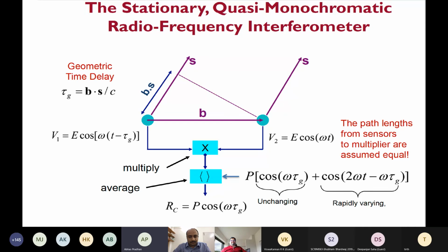So is this calibrated beforehand? Is this correction determined before, or is there a real time correction where we timestamp? This is inbuilt because you know your array, right? You know the B's, the exact spacing between antennas. The only thing unknown is, for that particular timestamp, where you are looking. If all the antennas are looking in the same direction, that is also known to you, so you can basically correct for that.